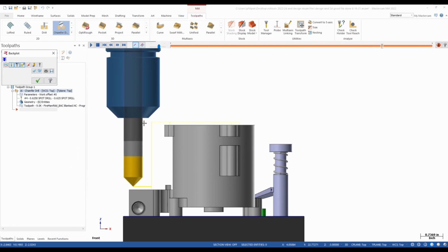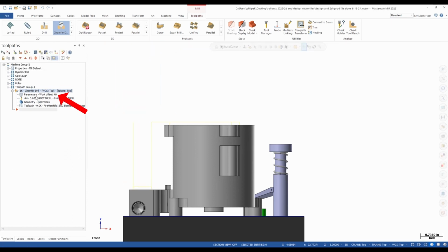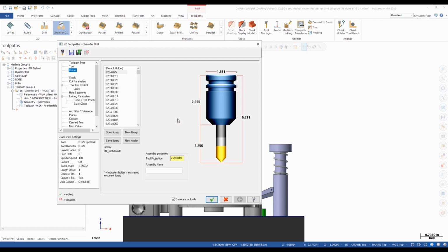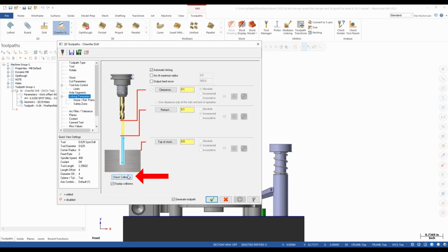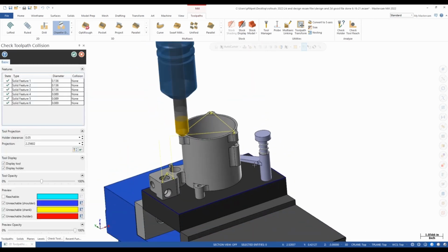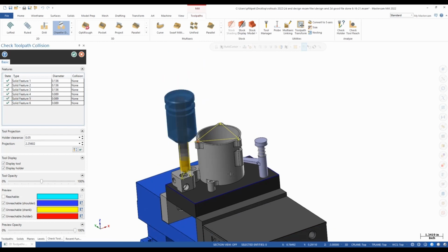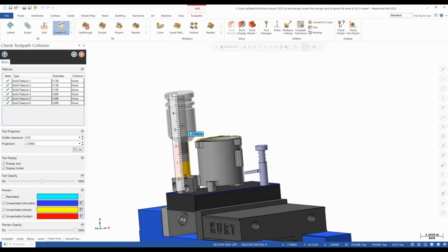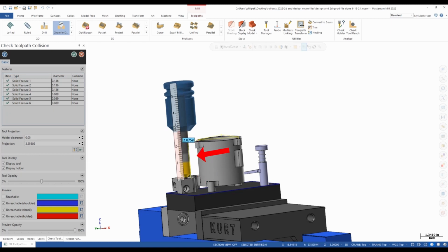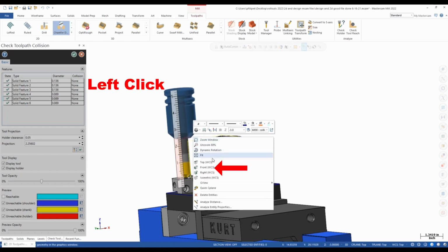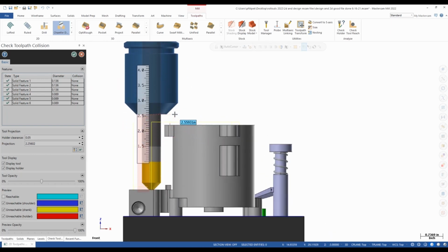There's one more feature in here I'd like to show. If we come back into our linking parameters page and check collisions again, one other option you would have is I can hover over the holder, left click, and now I can drag this wherever I want. So if I wanted to eye this a little better, or maybe not have a collision between a clamp or something else that I'm not checking against, this would be a good option to use the ruler or manually move it up and down with your mouse, and then just left click, and now your projection would be that value.